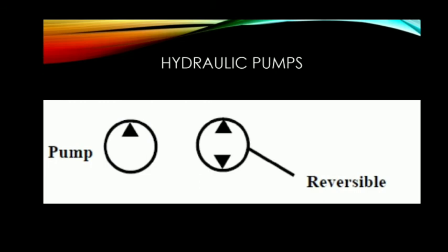Motors work exactly on the reverse principle of pumps. In motors, fluid is forced into the motor from pump outlets at high pressure. This fluid pressure creates the motion of the motor shaft and finally goes out through the motor outlet port and returns to tank. All three variants of motors, already described for pumps, namely gear motors, vane motors and piston motors, are in use.